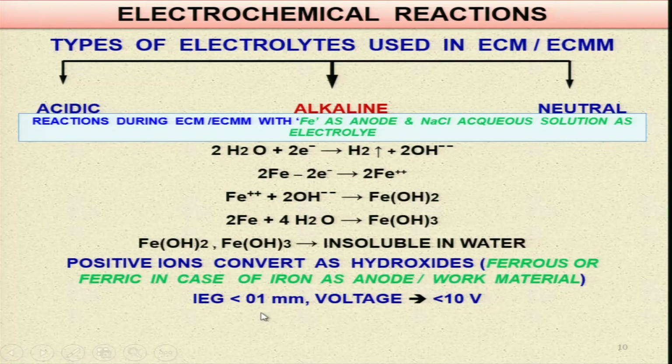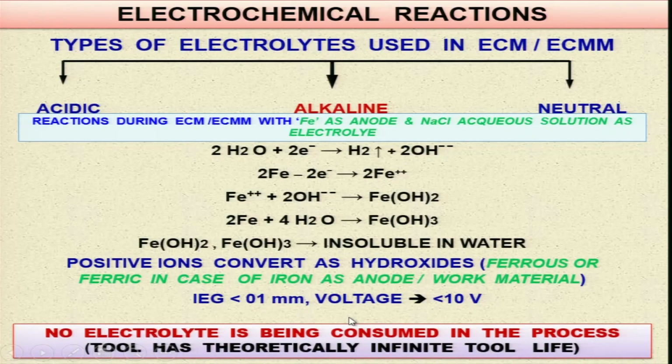Inter-electrode gap is less than 0.01 millimeter, voltage is less than 10 volt. Note it carefully, no electrolyte is being consumed in the process in this particular ECM as well as ECMM. Tool has theoretically infinite tool life because there is no dissolution from the cathode, that is the tool. But because of so many other things, the tool life in ECMM as well as ECM is finite.